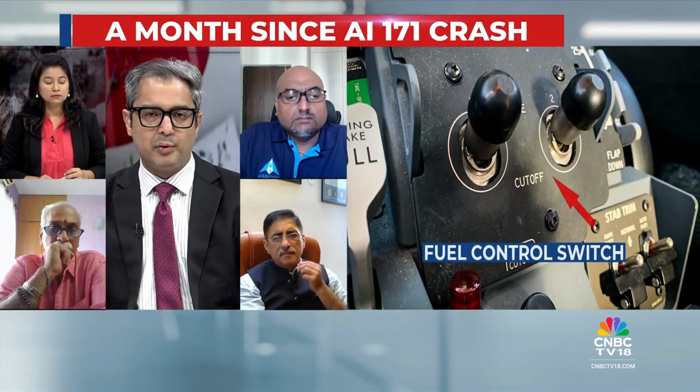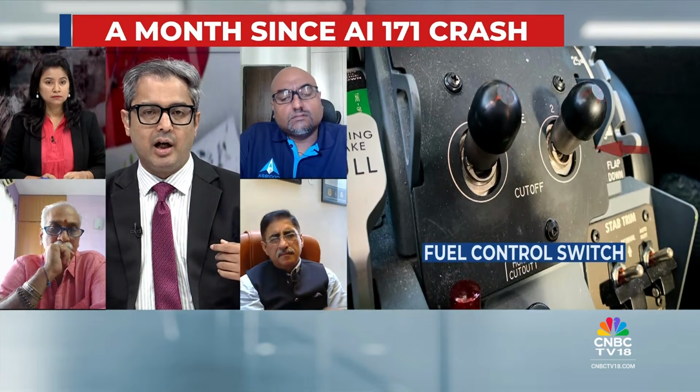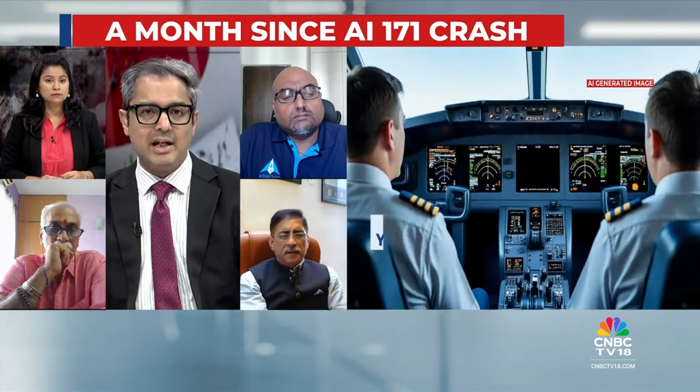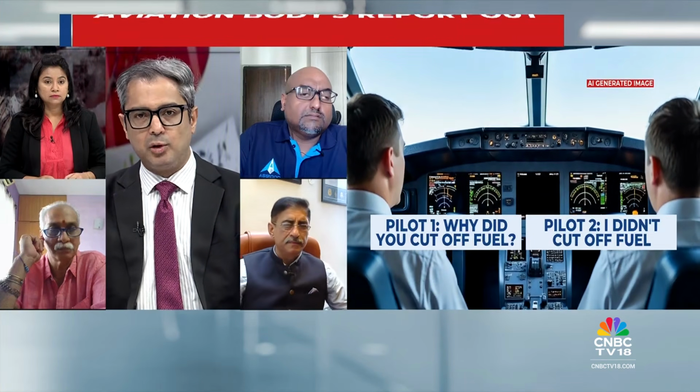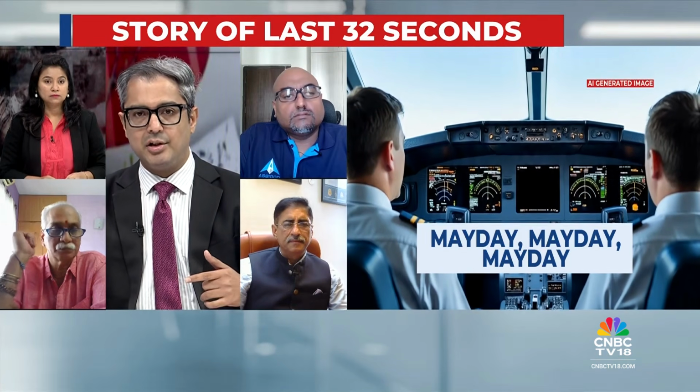But because the aircraft had not got enough liftoff, it had not got enough altitude. If it was 1,000 feet up, then this would not have been a problem. But the maximum height it reached was about 625 feet. So because of that, there wasn't enough time for the fuel supply to go back into the engines. I believe one of the engines then restarts. It's relit, but the second engine is not.